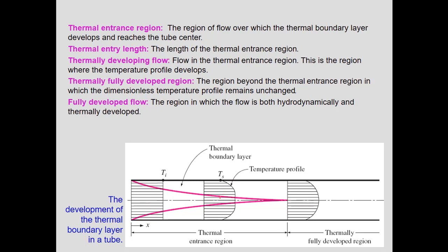So due to the heat transfer between the fluid and the pipe wall, its temperature profile will be constantly changing to finally reach something like this, where its temperature profile is fully developed. After this point, the temperature profile doesn't change. It will be something like this. Temperature near the surface, or in contact with the surface, is the same as the surface, and at the center it is different. It depends on the temperature difference between the fluid and the pipe wall.